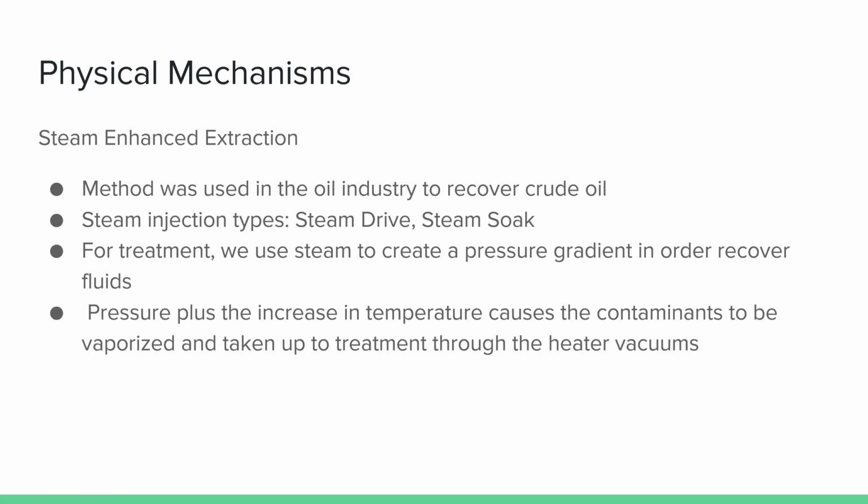Then lastly, we'll talk about steam enhanced extraction, which has its background in the petroleum industry, where we used it to recover crude oils from reservoirs. There's two modes of steam injection, one being steam soak, which involves the steam soaking and sitting into the area, while steam drive is used to push the crude oil out of the reservoir.